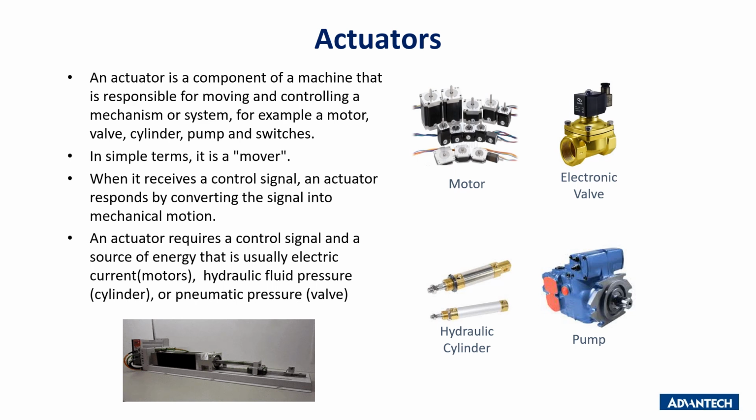Actuators. An actuator is a component of a machine that is responsible for moving and controlling a mechanism or system, for example a motor, valve, cylinder, pump and switches. When the actuator receives a control signal, it responds by converting the signal into mechanical motion. An actuator requires a control signal and a source of energy that is usually electric current for motors, hydraulic fluid pressure for cylinders, or pneumatic pressure for valves.